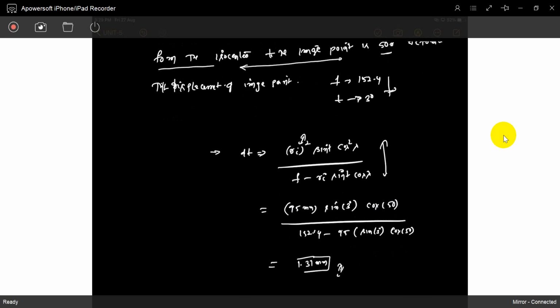So you can't get 10 mm, 20 mm or 10 meters, 20 meters, because in the photograph, the position of the point from the isocenter, how much is changing when we took the photograph vertical versus from a tilt photograph. Just a small change will happen, because the tilt angle is 3 degrees, not 10 degrees, 20 degrees. Very small tilt angle of 3 degrees. That's why the position is changing by 1 mm. In reality, just 1 mm is changing. That is the idea.